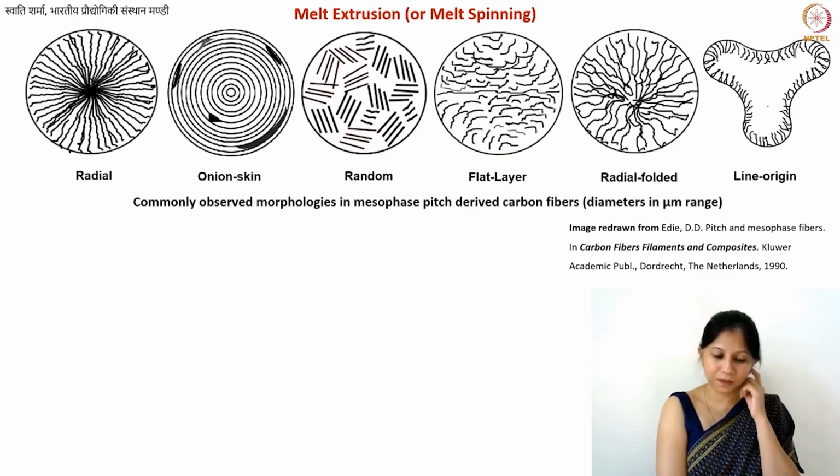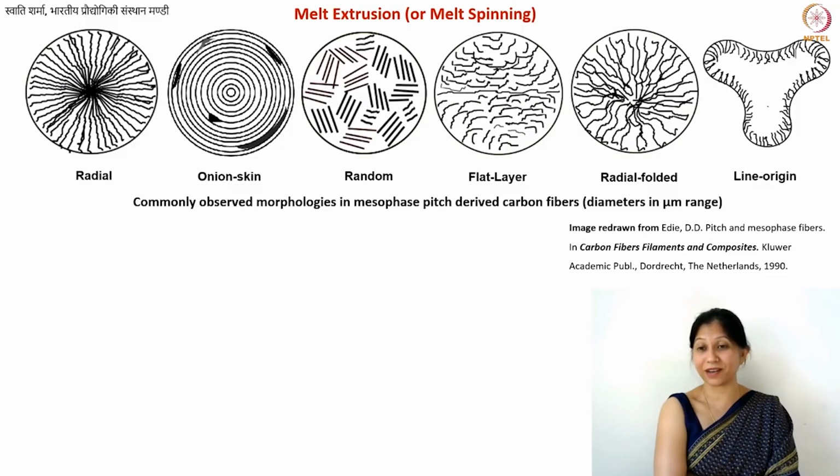In fact, this term is also industrially used. You will hear the word graphite fibers. Be careful, sometimes industrial fibers are not really graphite, they are just graphitic, but in the terminology they call it graphite because graphite sounds more sophisticated and also more costly. So often the terminology is used in a wrong fashion. Anyway, that is not our concern. For you, it is important to know that if you have very high crystallinity, then you can call it graphite fiber, not graphitic fibers.